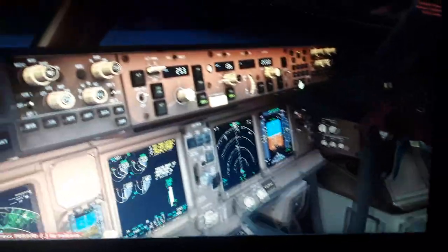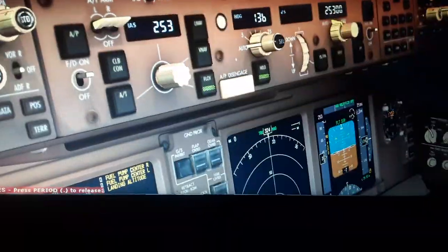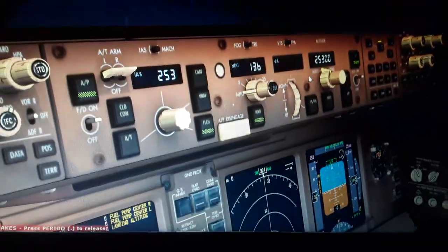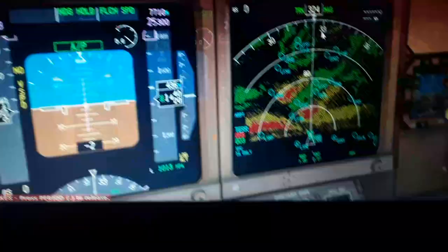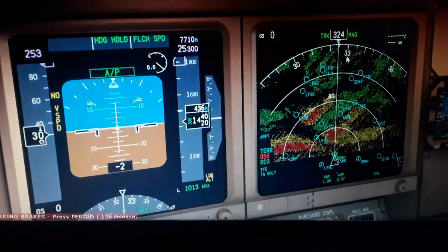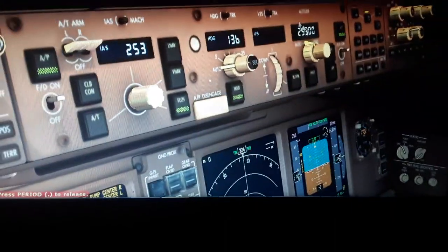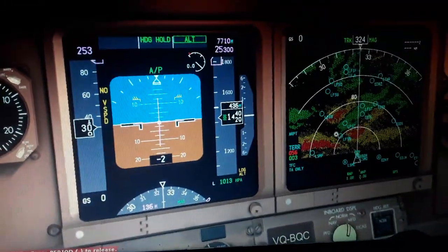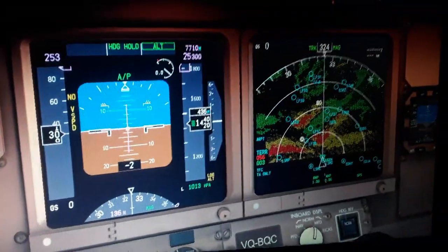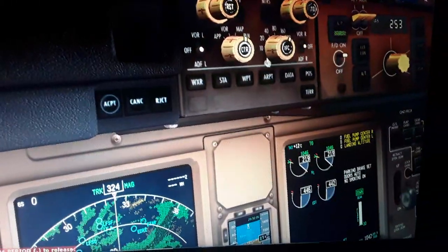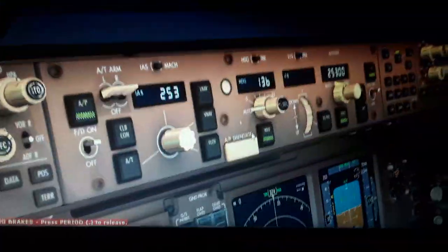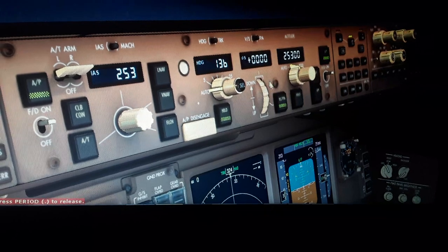Need to cover up. So we have also auto throttle, autopilot on, heading. So we're gonna have the autopilot on now. Flight level change, speed. We can set also the altitude like this, 35,300 with the autopilot on. And the altitude, you can see also the terrain, the scan from the radar. So we have also the vertical speed of flight path angles.